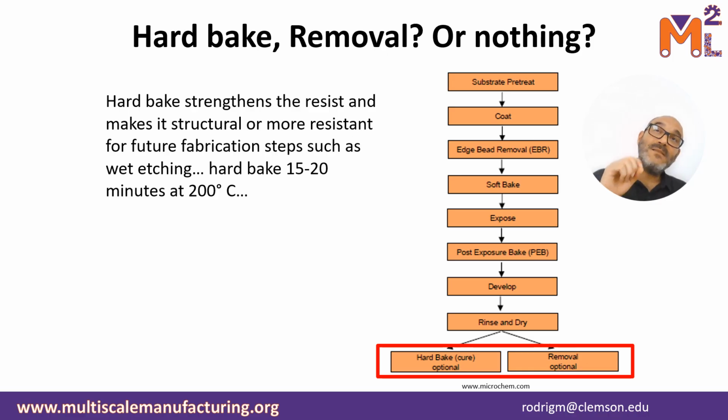This was particularly important when I was using fused silica. With fused silica, that hard bake seemed to have a crucial effect on whether the SU8 pyrolyzed well or not, right? So that will be something for you to consider.